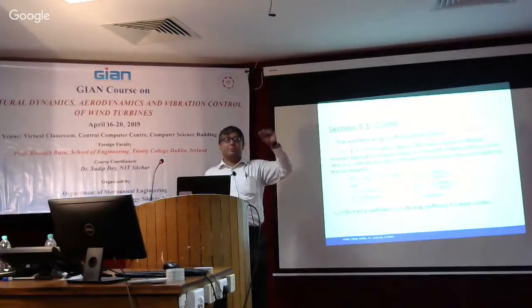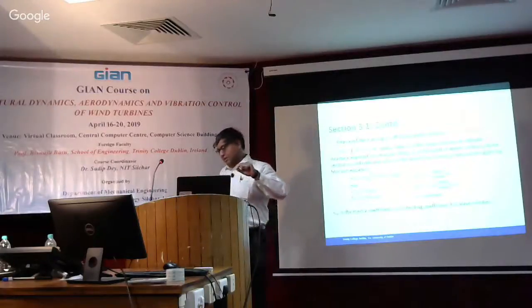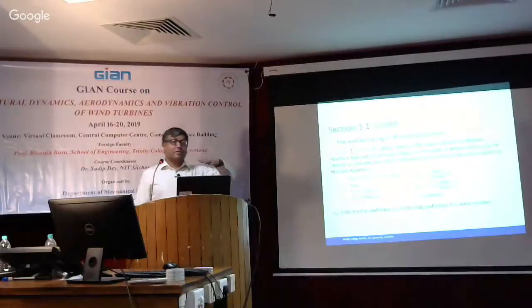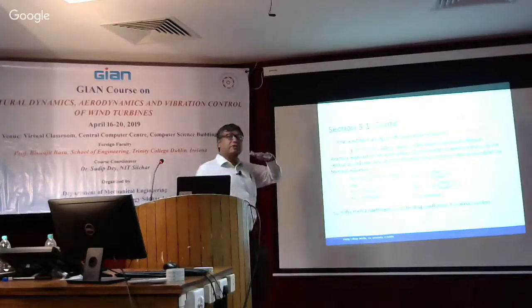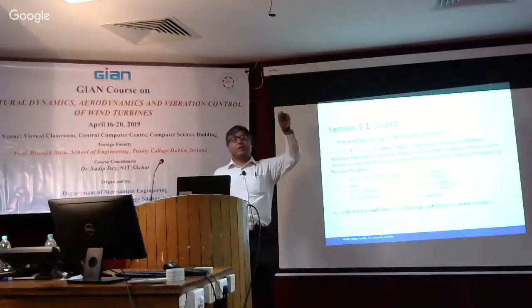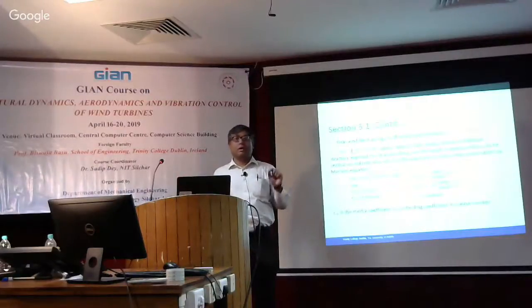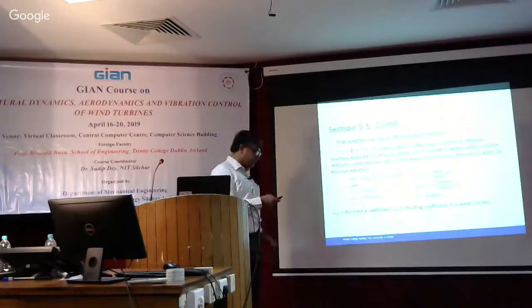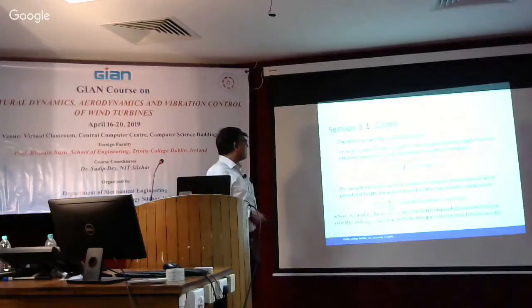Because if you remember, your log or power law profile will require wind velocity at a certain height. And so you use that U10 and then use that value to get your profile for the log or power law and generate the wind profile. That's how it should be for the coordinate. And the wind speed at 10 meters, U10, and the significant wave height from the JONSWAP spectra, Hs.